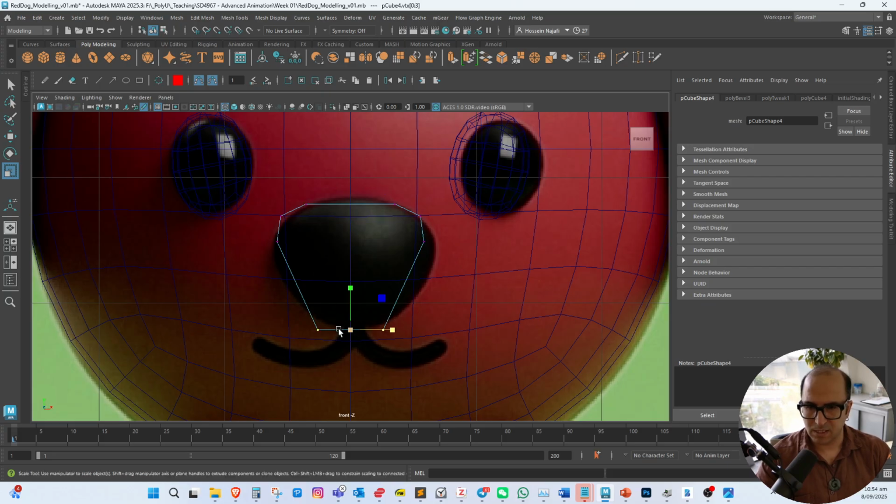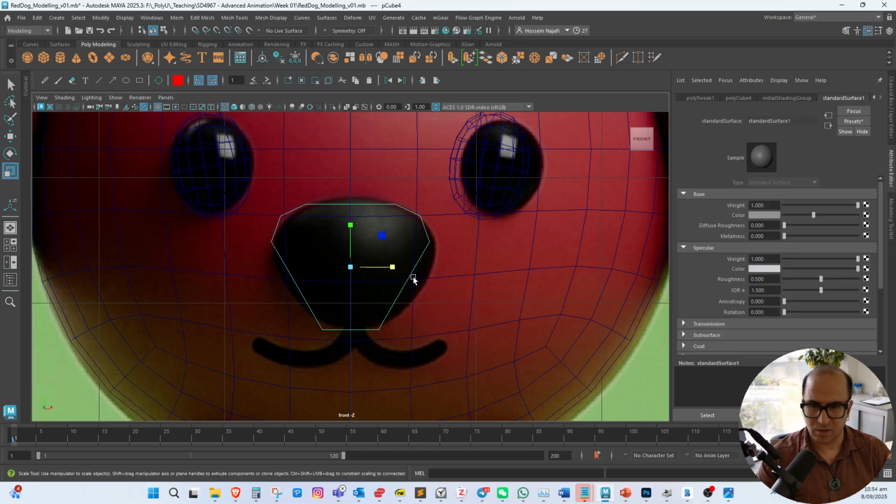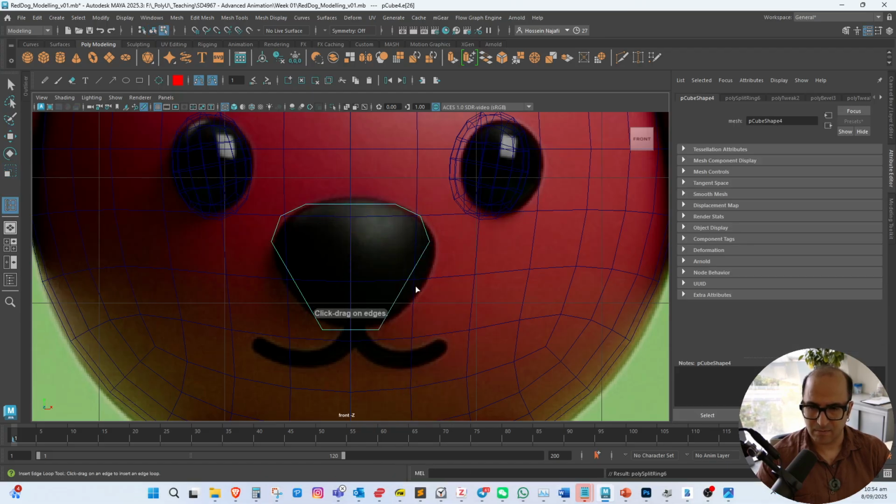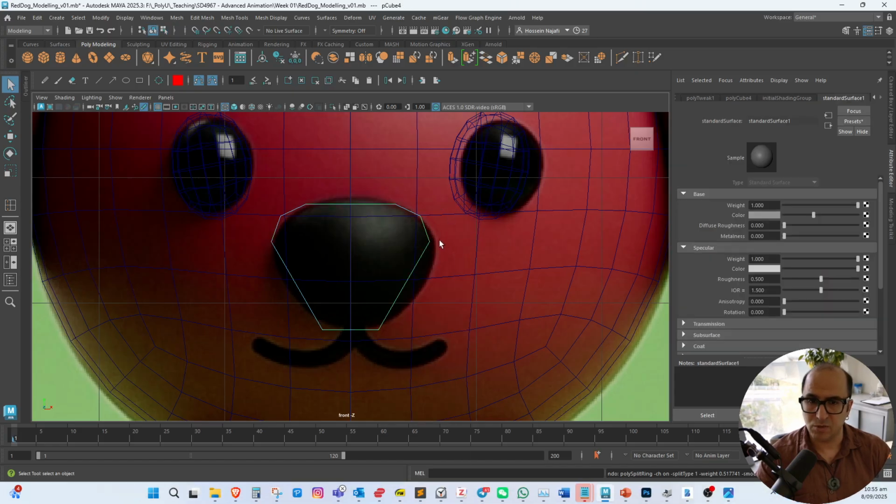So here you see that this part is closer to each other, but I need some part further away from each other, so these 2 parts I box drag them further away, but I need some sort of more detail here. So I go to the object mode, shift right click, insert edge loop. I can't add an edge loop here for some reason. So I'm going to introduce you to a new tool.